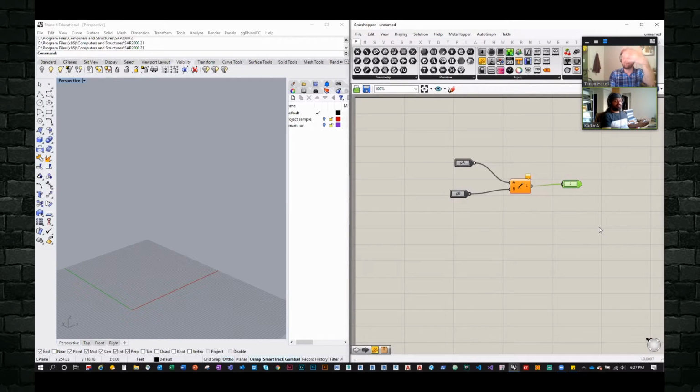How to make these clusters that you're putting on the toolbar. Yeah, on the panel. So then you select them after you establish your inputs and outputs, and assuming that what's inside your cluster is something a bit more complex than just one node, that would be a waste of a cluster. Just click cluster, right? So you just select all of it, click your mouse wheel, and click on this cluster node, and that clusters it. So if you hover over that, it says point A, and in parentheses PA, and you can add a description. By default, it just says line start point, because that's what it plugged into, in the native Grasshopper node.